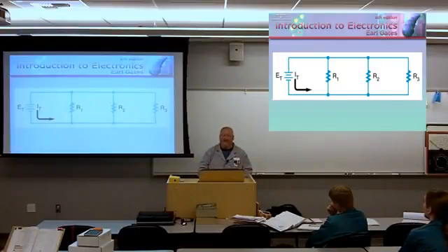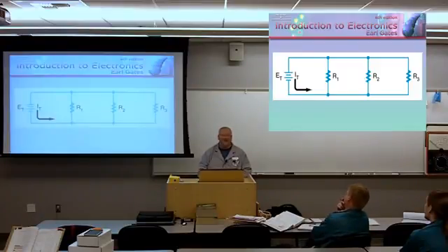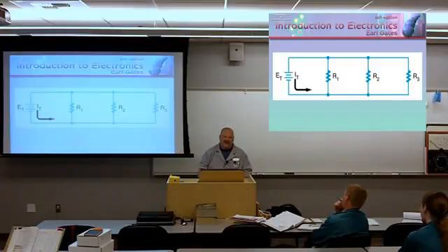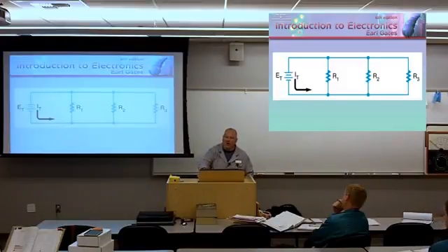But I could tell. If I brought you back there, you probably wouldn't even notice it. But I could tell which light is the furthest from the power supply. Just looking at it. And it kind of bothers me. It doesn't bother me enough to rip up the conduit and pull new cable, okay? But I know by looking at it. And what does that tell me? That tells me that the load furthest down the line is not getting the same voltage as the load closest to the source. And gradually, as you get further away from it, you just notice a little difference in illumination.